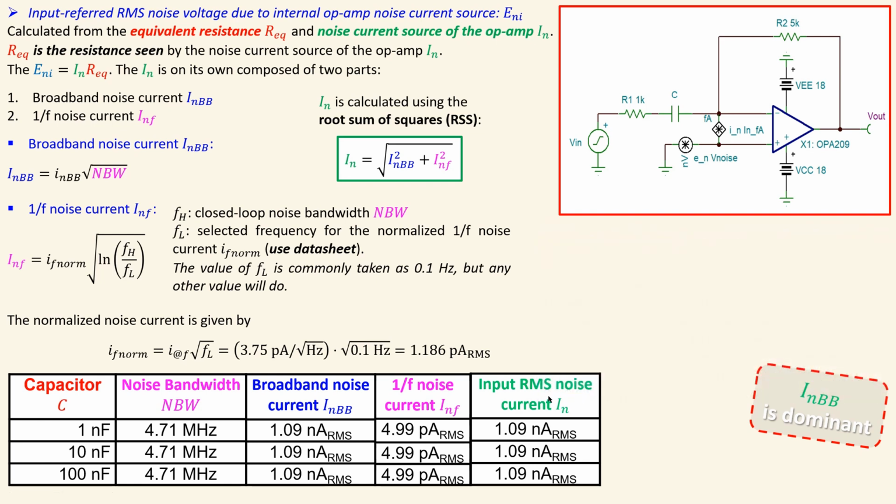Now, if I want to calculate that equivalent resistance, because this is just given in amperes and I want to move to volts, let's use the equivalent resistance in this circuit, and that is the parallel combination looking from the source, the noise current source. It is a parallel combination of R1 and R2 using this formula. Again, I have 833 ohms.